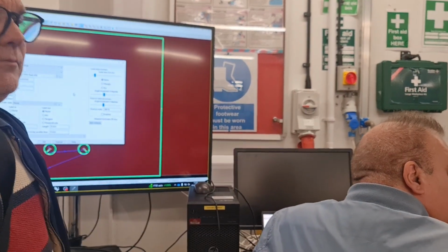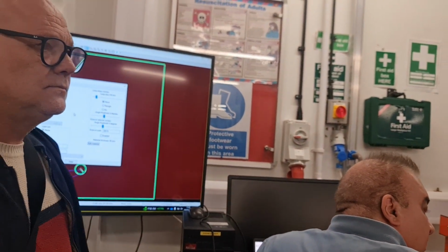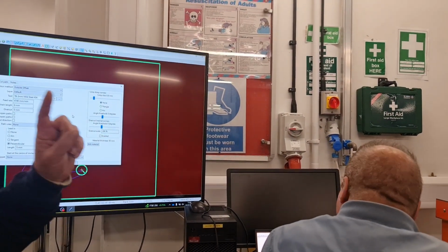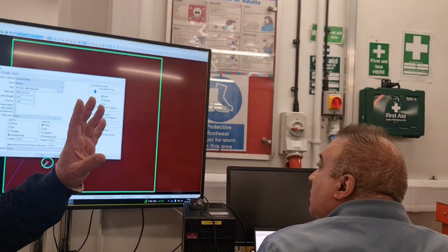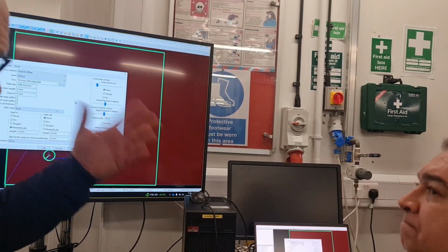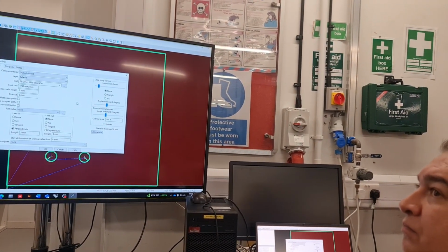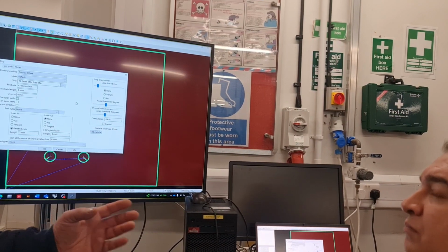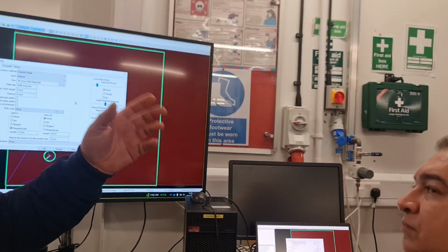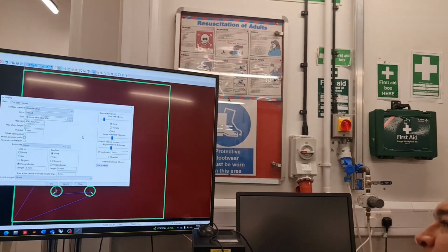You're talking about the margin cut. No, just if you didn't want to cut the outside border. If you have the file generated in one layer, you cannot say I don't want to cut the outer layer. You have to make a file with 2 or as many layers as you need. For example, you have drills of 2 millimeter, you want it with tool 1. Drills of 6, you want it with another tool. That's part of toolpaths for that.